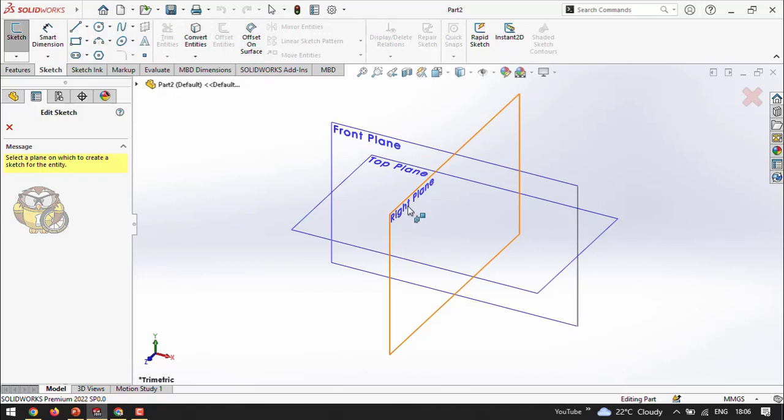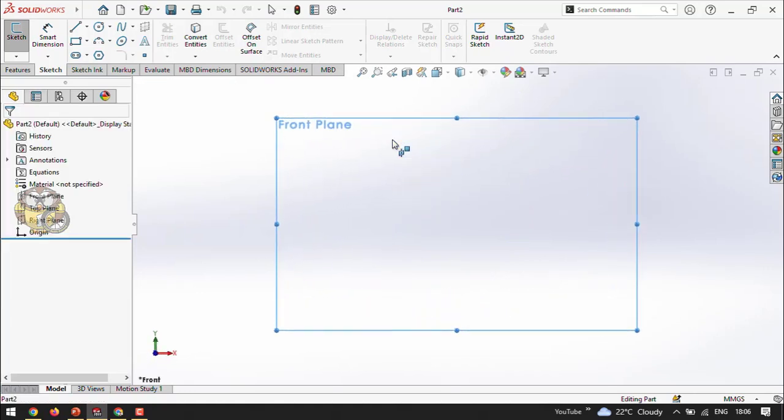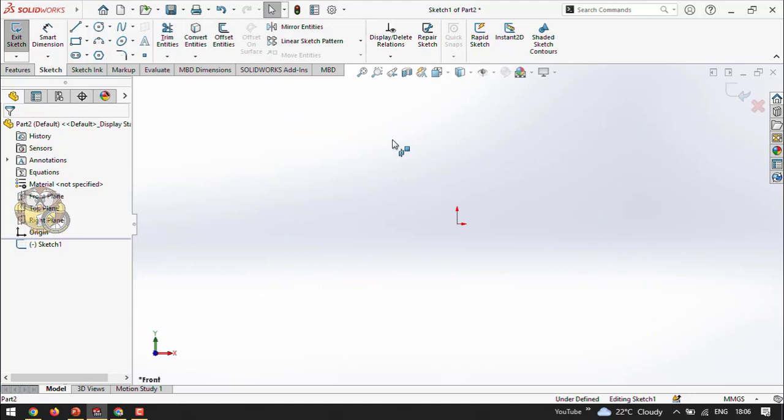If you cannot, no problem. After creating 3D models also, we can create some different types of planes. But as a good practice, you want to select based on your drawing. So this is our first class. I just select the front plane. It's automatically oriented.